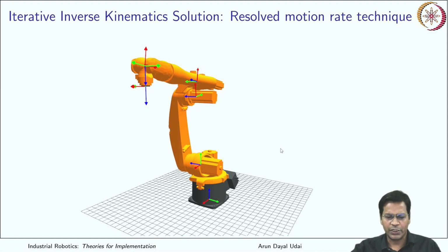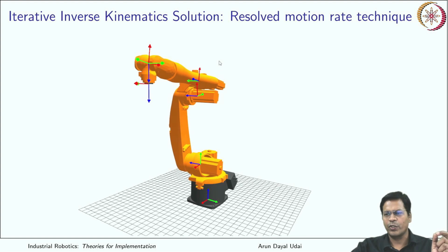This sort of motion can be achieved using small incremental steps. For such a small distance like 70 mm, I have divided it into something around 100 steps. So it is a very, very small displacement it is doing, and that is why it is able to do it. It can reach where I have commanded it to go. So this type of method works, at least for small incremental distances and slow velocities. You can very well attain this.